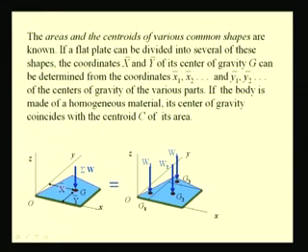If W1, W2, W3 are the weights of these plates, then the first moment of all these quantities with respect to, let us say, this axis OY, the sum of all these moments, is equal to the moment of this single force, which is nothing but the sum of W1, W2, W3 times the moment arm.